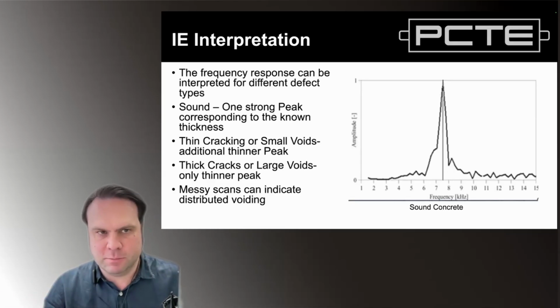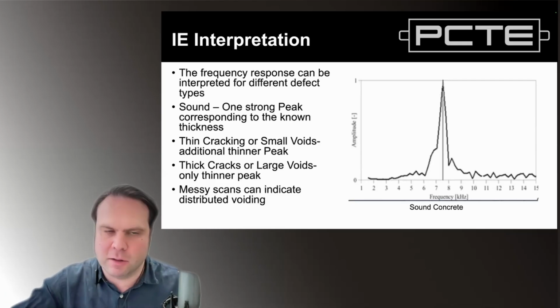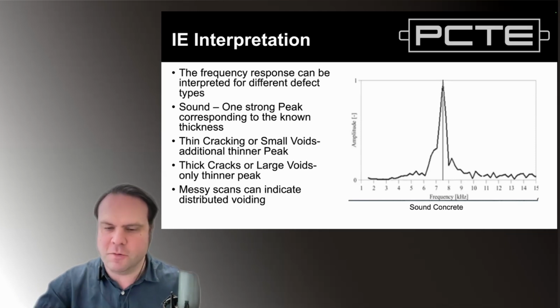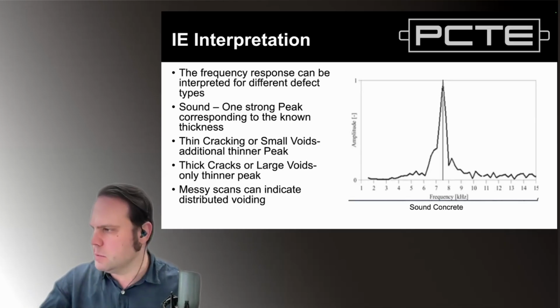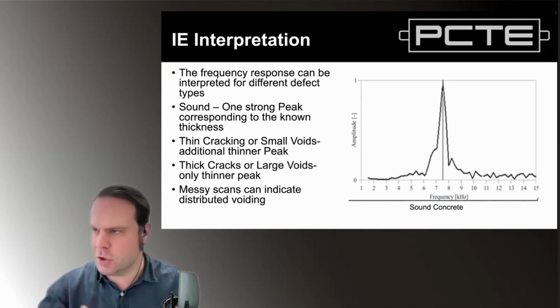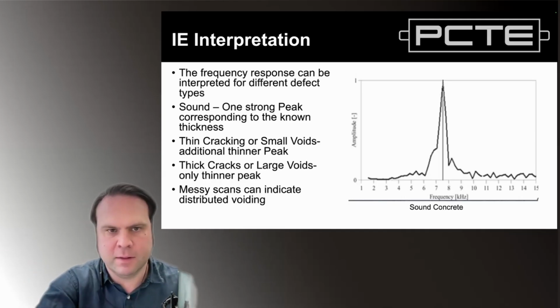The most typical way to do an impact echo test is to establish a typical frequency, maybe presented as a typical thickness over your plate element, your wall or your floor. In this case, a single frequency response without too much other input, around 7,500 hertz.